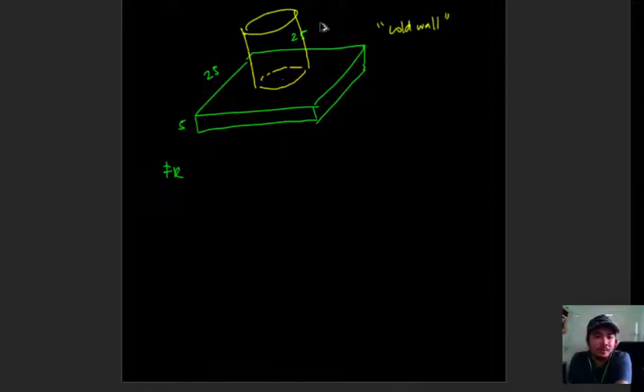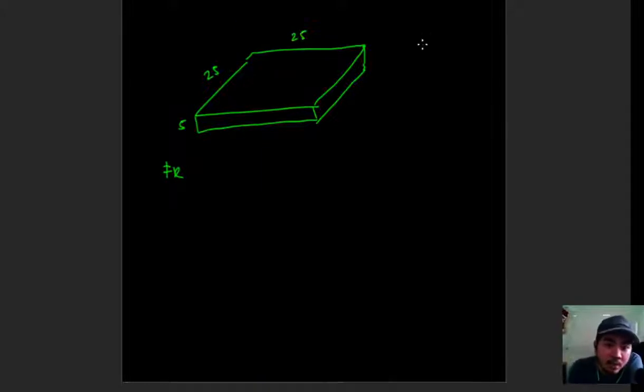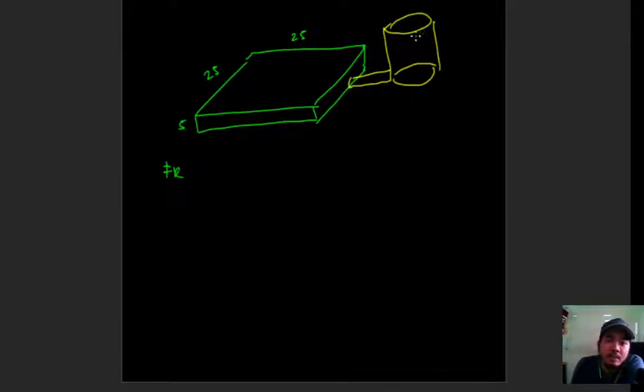So I think for now, let's do something simple first, no? We will not consider the deductions in the surface area yet. We'll just consider it as a side riser. A side riser, and I'll show you the benefits of the different types of risers later on. A side riser is basically a riser placed to the side of the casting, and you feed through a channel. Okay, so in this case, this is your riser, and it will feed towards there.